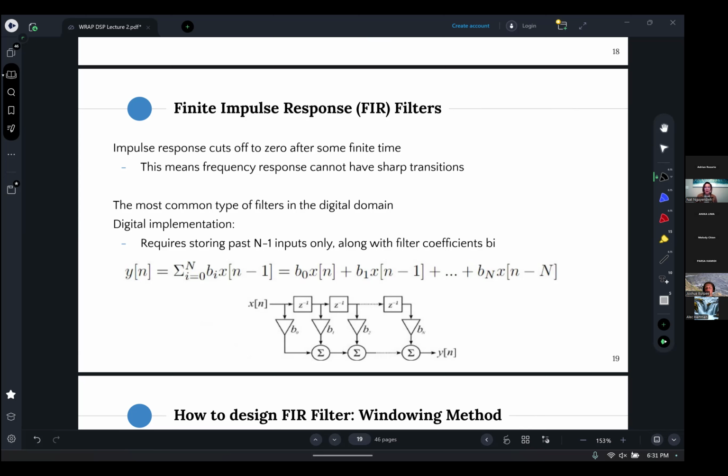Our impulse response, instead of the regular continuous functions we're used to, is going to look like coefficients, because they're just discrete points if we sample the impulse response at a constant rate. So when you expand this function out, b is going to be the coefficients, and x of n is going to be the nth input, the nth piece of data in our array.